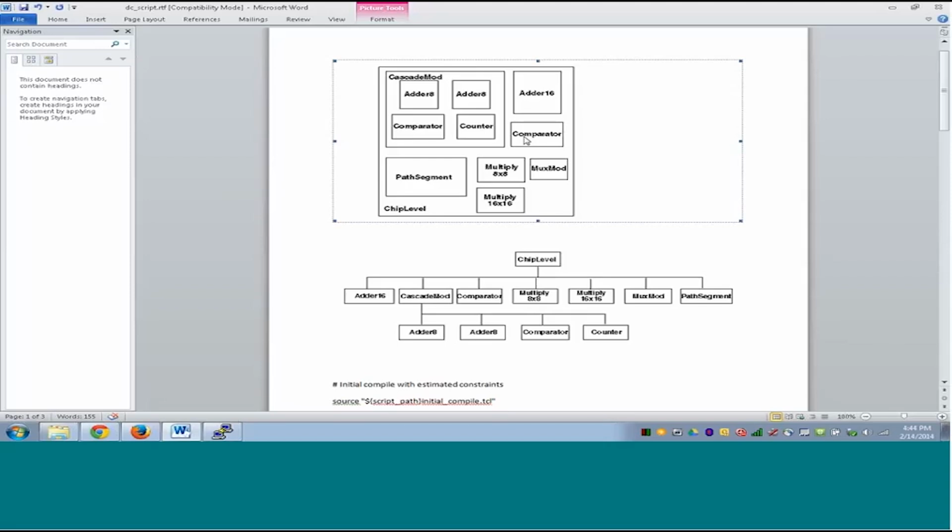Why? Because nowadays in industry different design teams own different intellectual property. Some team would own USB, some other team would own HDMI. If you are synthesizing the chip, every time there is a design change in HDMI, you are also synthesizing all the other IPs. That's why the bottom-up approach makes much more sense, wherein we synthesize the underlying designs first, and then at the chip level we set these designs as don't touch and compile the chip level.